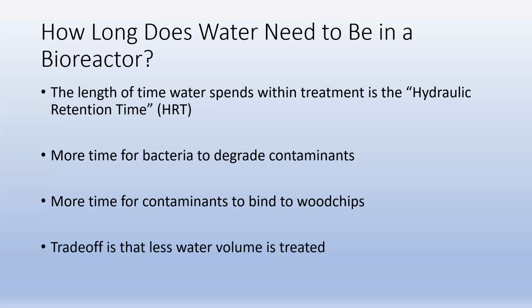Now, the trade-off is, if you let water sit in there for super long, you're not going to treat a whole large volume of water. If you let water go through super fast, you're going to get a little bit of treatment, and maybe not as much as you want, but you'll treat a very, very large amount of water. So these are some trade-offs you have to consider.